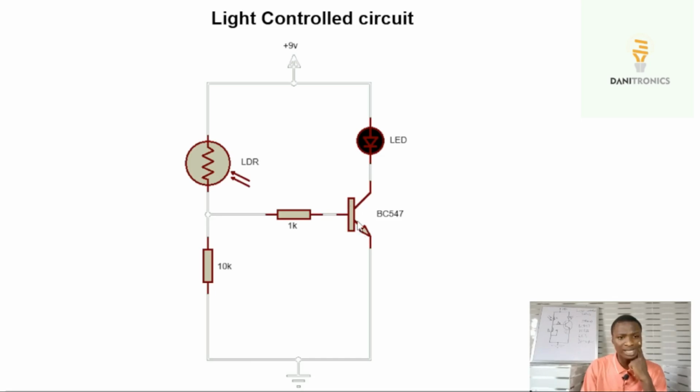Now you should understand that in my previous lecture I explained voltage division, where we had resistor R1. That's lecture number 7. You can check it out to understand this concept. I explained voltage division, and I told you that we had resistor 1 and resistor 2, and if you want to get a voltage in between the series connection, there's a formula to do that. I gave us the formula in that video. So whenever two resistors are connected this way, there will be a voltage drop here, and that voltage drop will be used to switch on this transistor and in turn switch on this LED.